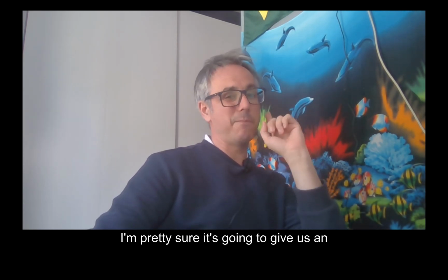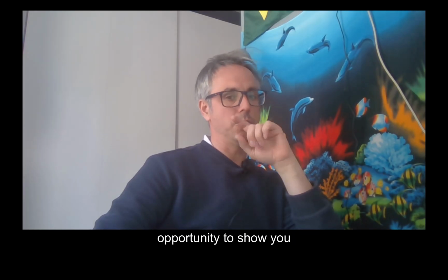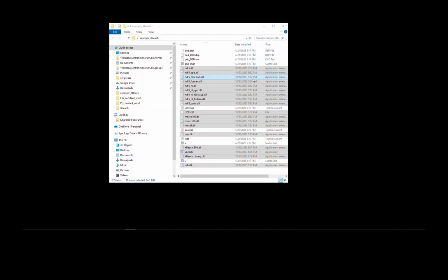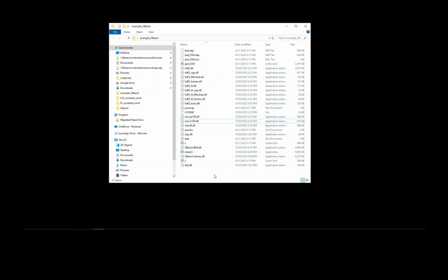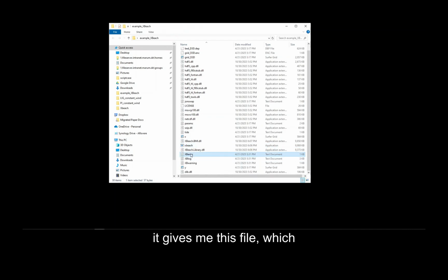So let's run it. I'm pretty sure it's going to give us an error, and it's going to give me the opportunity to show you how to debug. So let's go there. This is the folder, example XBeach, where I copied everything. I look for this XBeach and I just double click on it. And you see that it ran for just 1 second. I'm not even sure you saw it. And it gives me this file, which means that there is an error in my model.